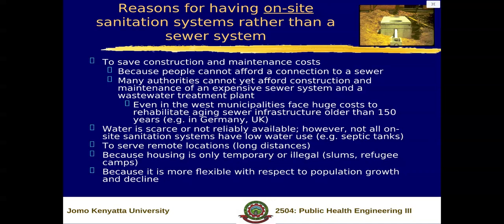It's an expensive system. But if the water is near your house, then you can treat it and reuse it, because the wastewater does not require another transmission and pumping. If it was going by gravity from Dandora, to take it back to Karen you have to pump it. So it becomes more difficult to operationalize reuse.